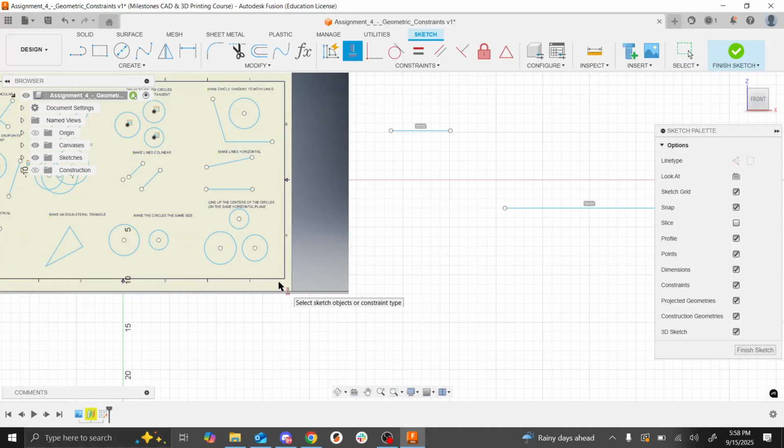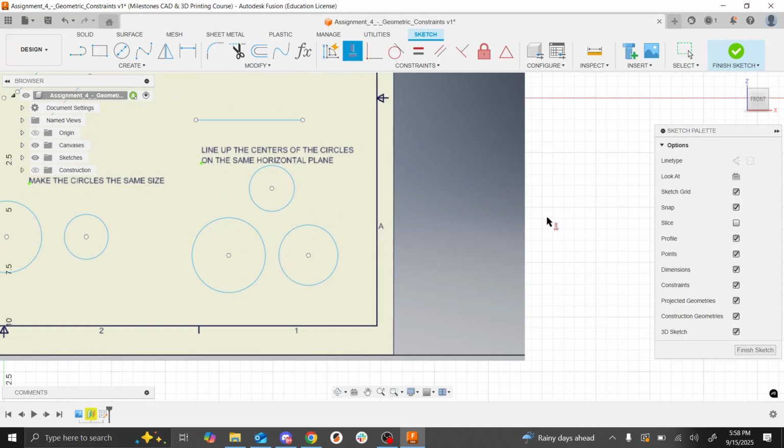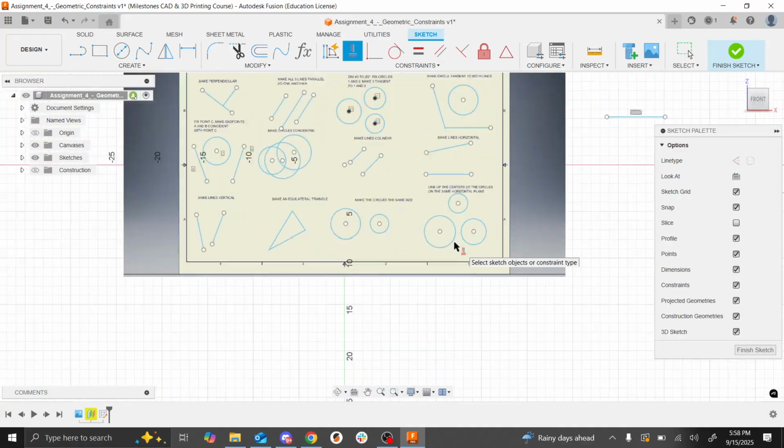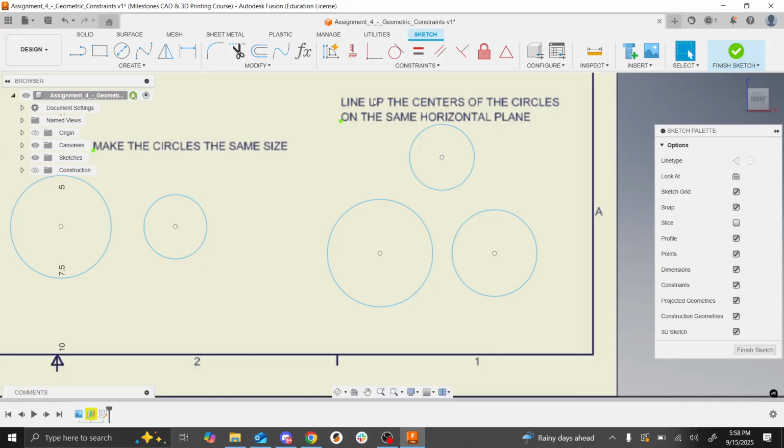Yeah, I mean it's just kind of a CAD thing too. Someone was having an issue with the last one in the bottom right. You can actually constrain circles through the actual circle or the center, right? So if you wanted all of these to be horizontal to each other and you applied the vertical horizontal constraint to the center of the circle and then this one, you can see that it snaps to vertical because that's the quote unquote easier path for Fusion to take.